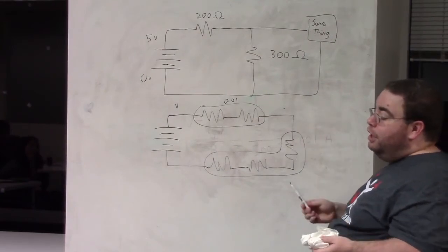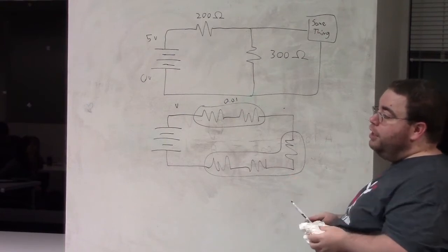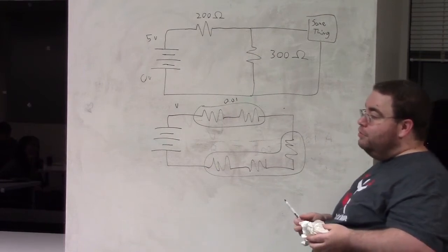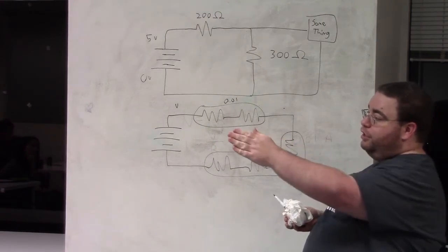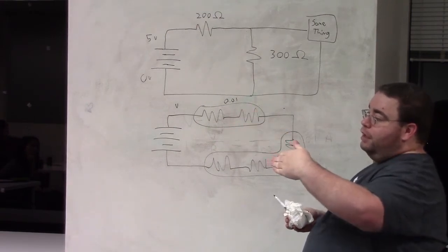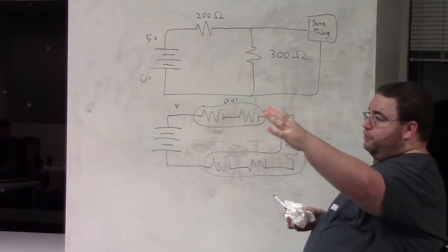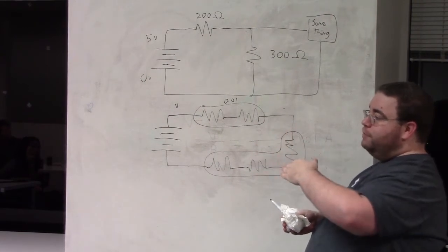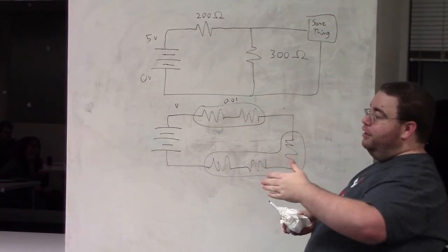probably better. The other way to drop to 3 volts is a part called a Zener diode. I don't want to get a whole lot into that yet, but a diode is a thing that will only send current one direction and block it the other direction. Most diodes have a breakdown voltage where over a certain amount of backwards voltage, they will let it through anyway and then catch on fire. Zeners are special in that they will let it through anyway but not catch on fire.